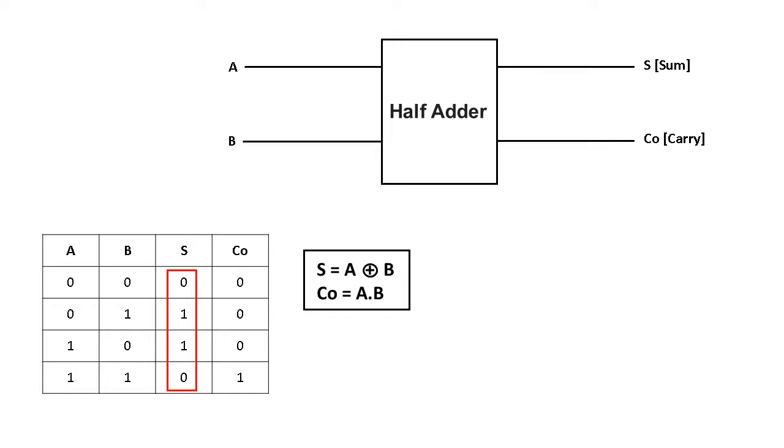As per the laws of the XOR gate, if an odd number of ones is detected, then we are going to achieve a high output. In the second and the second last row there is a high output achieved from a single one, that is the odd detector, and in the other rows we can see two low inputs in the first row and two high inputs in the last row, both resulting in a low output.